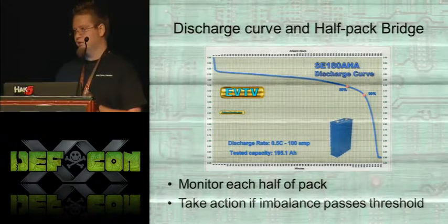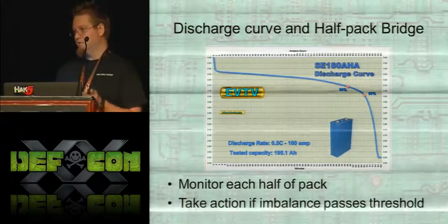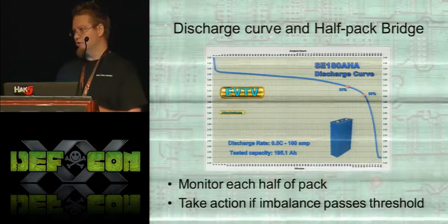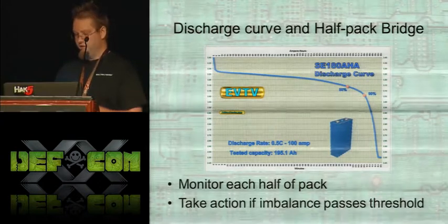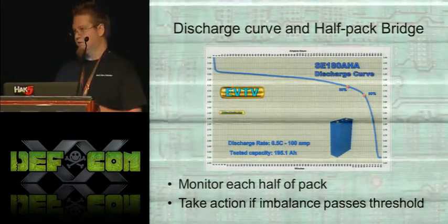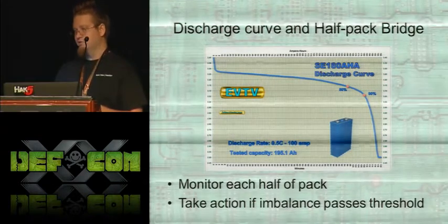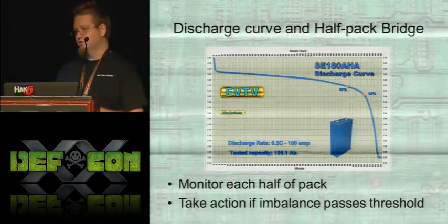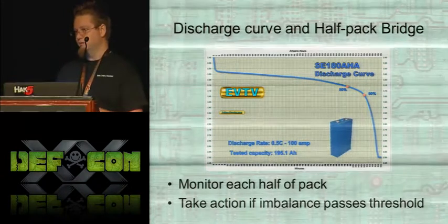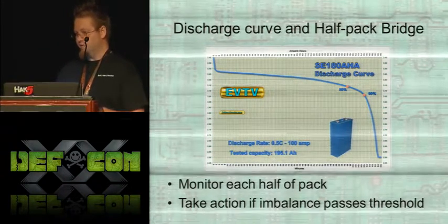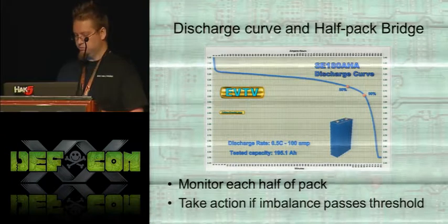So some people make a circuit that can either disable their battery pack or turn on a warning light or something to let them know, and that way they can take action. Or you can just have a couple meters monitoring that for you and just pay attention to it. Obviously, if you're only using, say, 70% of your capacity on a regular basis anyway, you don't really have to worry about anything, because you won't be getting close to those ends.